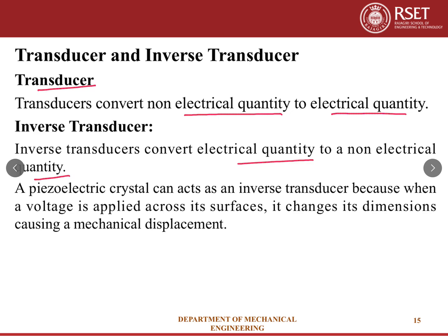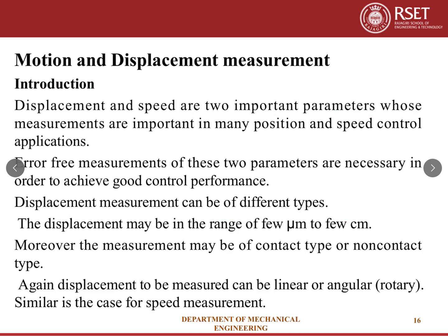So a piezoelectric crystal can act as an inverse transducer, because when a voltage is applied across its surface, it changes its dimension, causing mechanical displacement, like mechanical vibration. When we take a quartz crystal and apply an electrical signal, it will vibrate. So the conversion from an electrical quantity to a non-electrical quantity is happening. So that is an inverse transducer. That is about the different classifications of transducers.